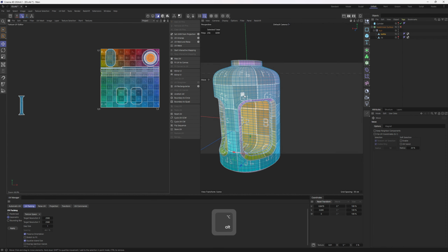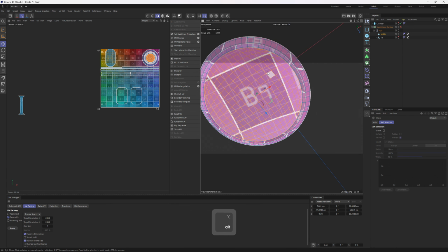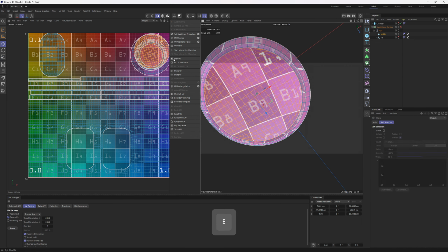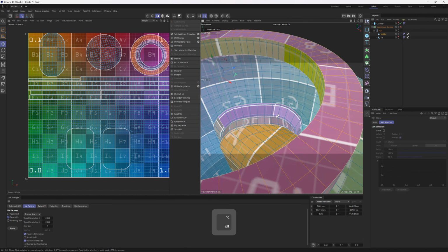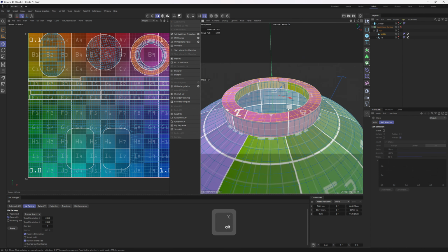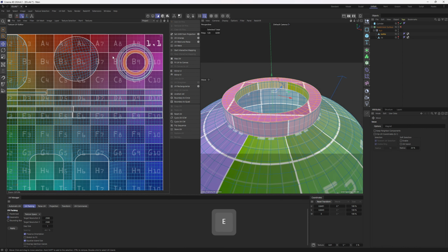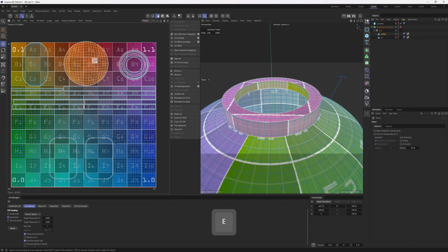By the way, for example, if there is going to be a texture on the selected polygons, the UVs of the selected polygons could be larger than the unimportant ones. For example, if you take that UV island, I don't think in any scenario that this section will have textures on, so you can just simply scale that area down and open up space for the important parts. By the way, let me align that island and scale that up.